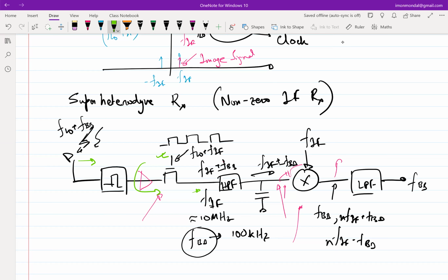So ultimately, the whole game is you have a wanted signal, and you have everything that is unwanted. How can we distinguish between the wanted and the unwanted, right? There are several ways of doing it. Filtering is one way of doing it. Here, fortunately, the unwanted part is something that is in our control, right? The choice of LO frequency is in our control.